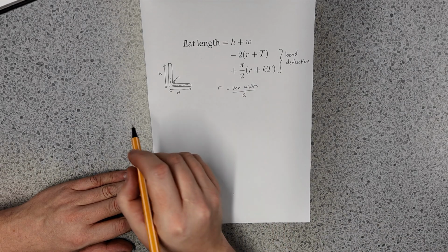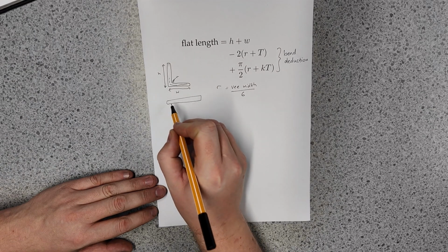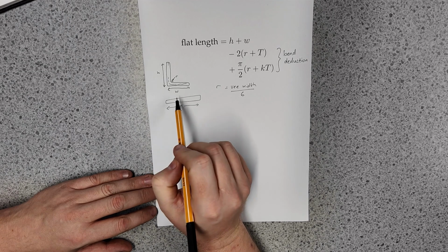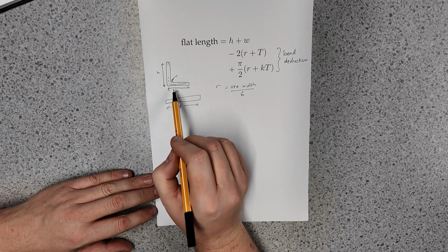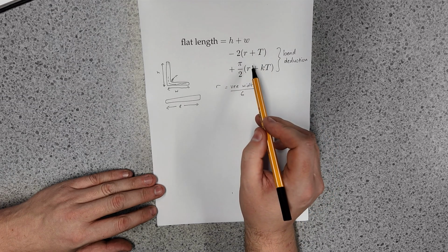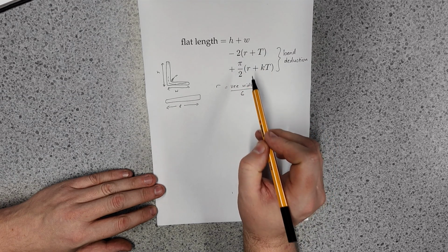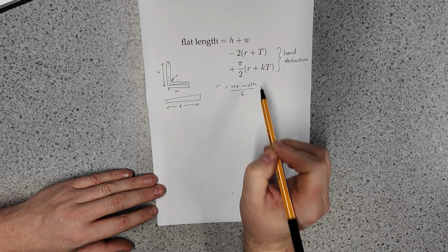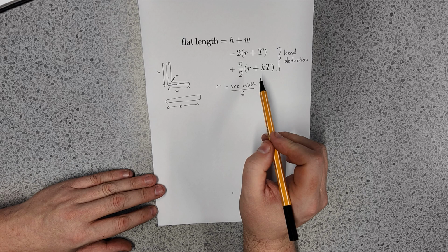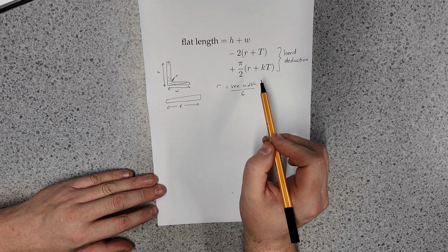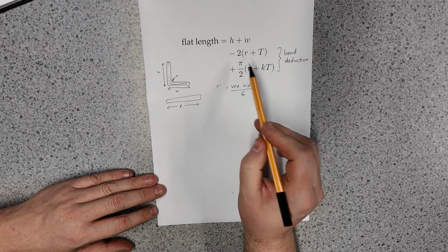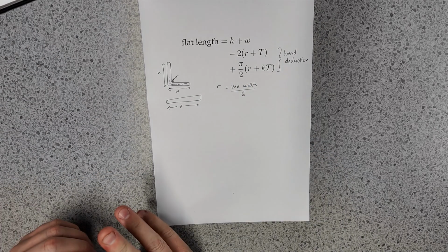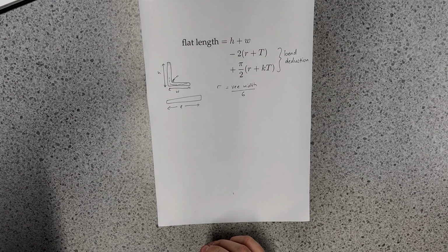We have a flat piece of known length L, we bend it, and we measure H and W, so we can compute the value of this bend deduction, and then solve for R and K. We'll need a whole series of measurements, at least 2, and we're actually going to do 8 measurements, and try to solve for R and K simultaneously in a statistically sound way. So let's get on with it.